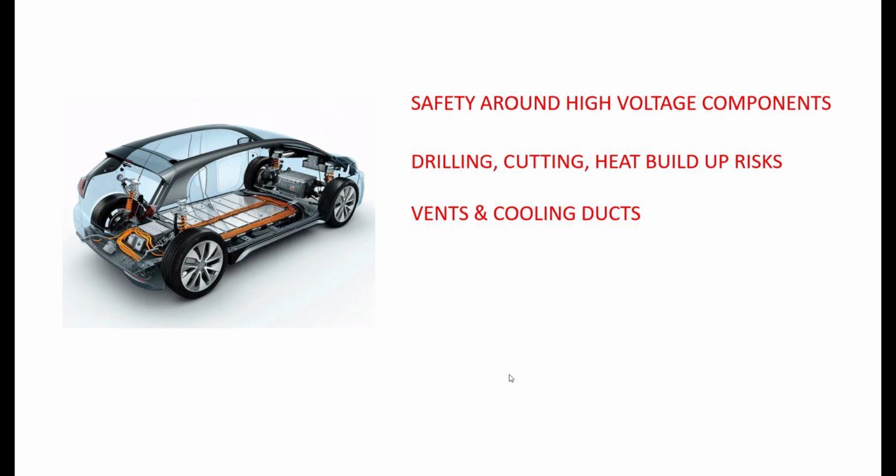It means be careful about where you're drilling and cutting. And I just talked about being careful with what you're doing when it comes to sound treatment, because you don't want to add sound deadening or butyl sheets and things like that, and then cause a heat build-up problem somewhere in your car. Often with hybrids and EVs, they have lots of vents and cooling ducts, particularly for the batteries and the electronic components.